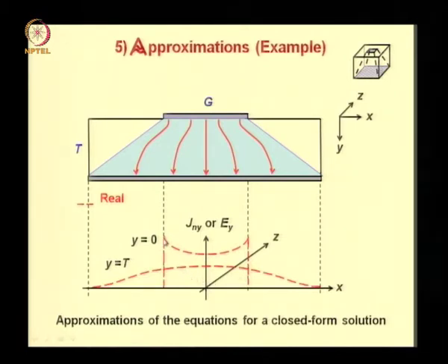Now the area under these current density distributions represents the total current. Please note that the current density is per unit area, whereas we are plotting it as a function of distance. So when I integrate this graph over distance, I will not get the total current, but current per unit length, because this is current density, which is current per unit area, and when you integrate over length you get current per unit length. So this is not really the total current. The area under these graphs does not represent total current directly, however they are a measure of the total current.